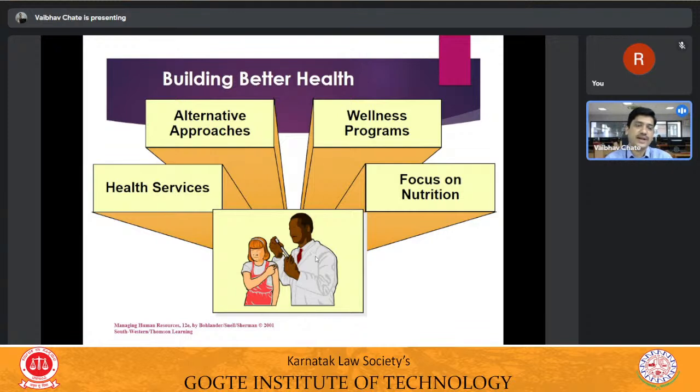Now, every time we may not use the fire water to extinguish the fire. Please understand. If there is a short circuit and the outbreak of the fire has taken place because of the short circuit, if you pour the water on the electrical lines, instead of extinguishing the fire, you are going to see that its intensity will get enhanced. So every time we will not be making use of water to extinguish the fire.